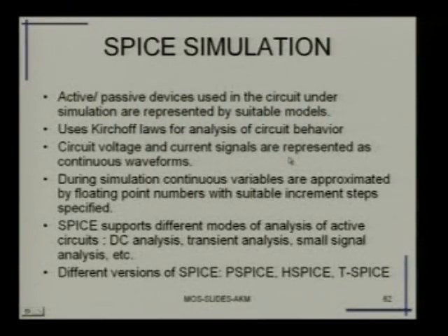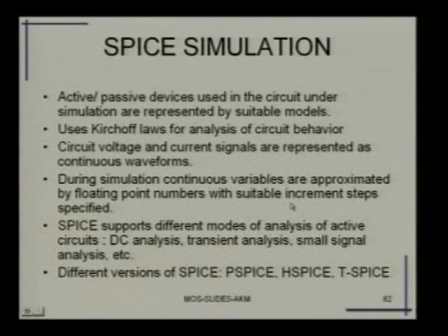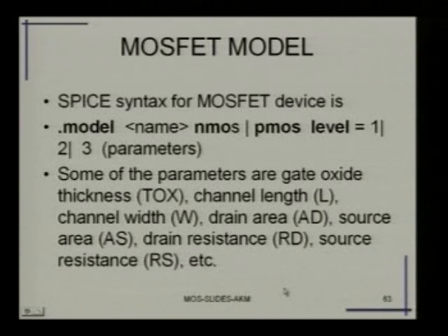You have to take into account the variability of the doping concentration, the channel length modulation and all those factors, velocity saturation, and using the models, then you set up the equations, and these equations will be highly nonlinear equations. So, they use iterative methods of solving those equations, and you do not have to bother.